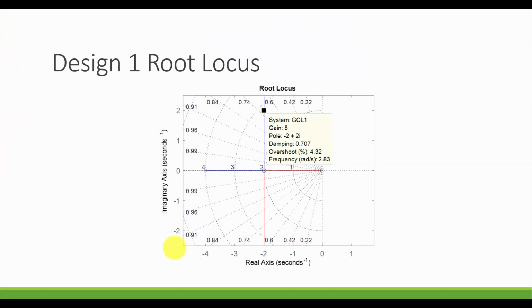And recreating it here on the slide. So that means that my closed loop transfer function is going to be, this is always true for the systems we're going to look at where we're ignoring the sensor and the actuator, KG' over 1 plus KG'. G' we established on the previous step where we chose the pole and the zero for the compensator, and now K we just found to be 8.